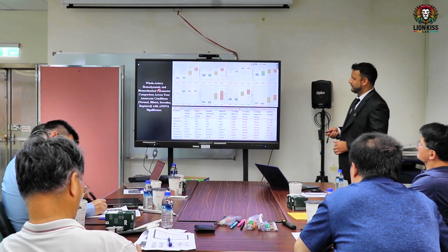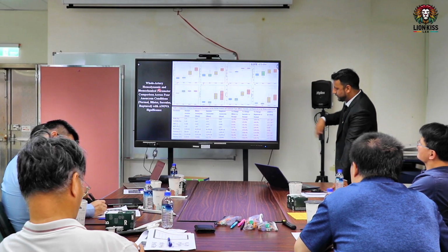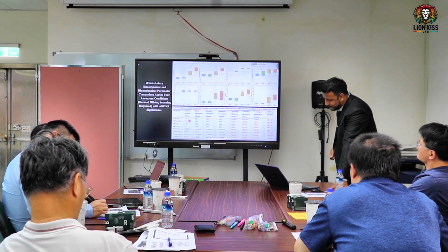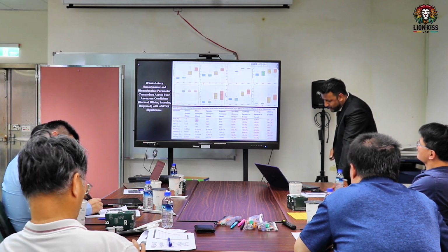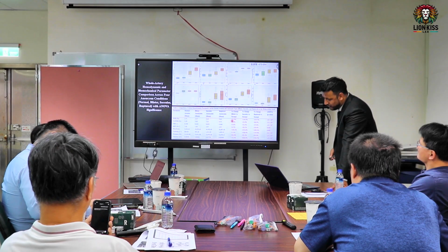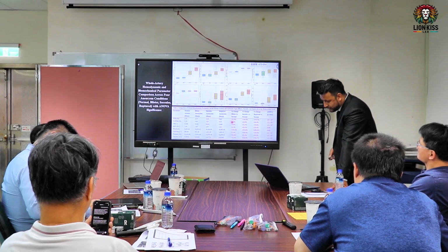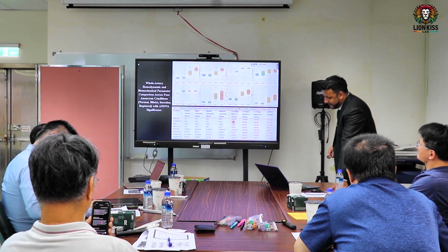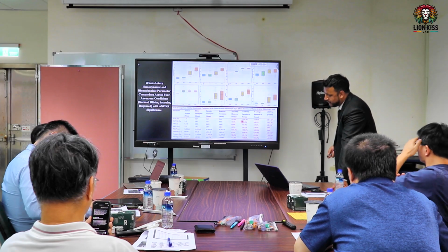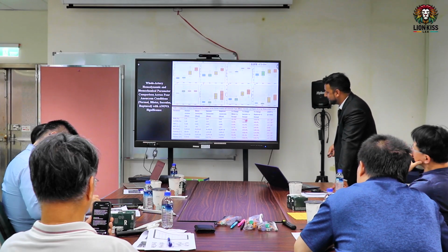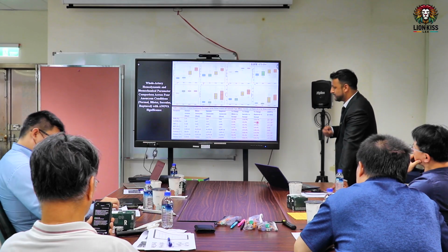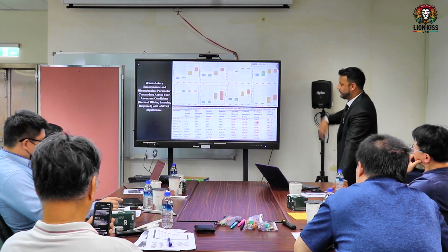When we measure the whole geometry of the aneurysm, we measure the relative difference changes. In the wall shear stress, with normal as our reference, the blister shows a 21% increase, the saccular aneurysm shows a 144 times increase, and in the rupture case the wall shear stress is 223 times higher. This is the comparison on the whole geometry.